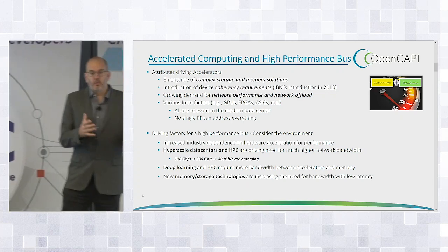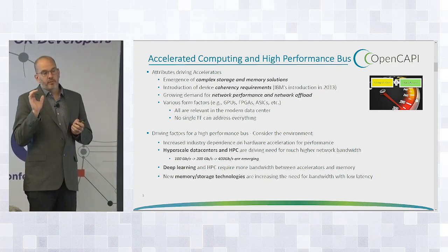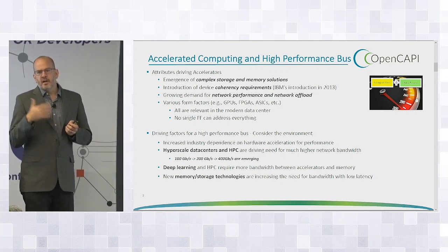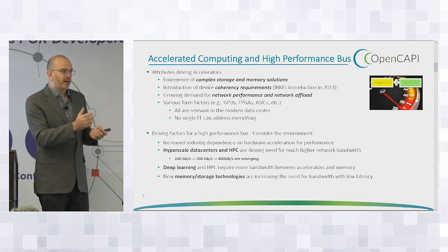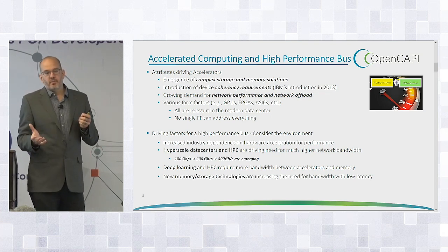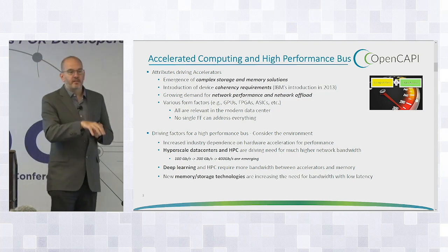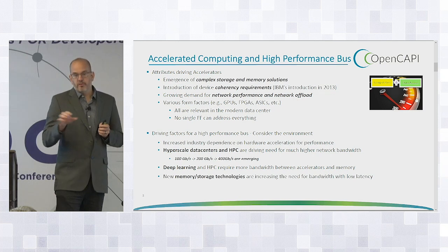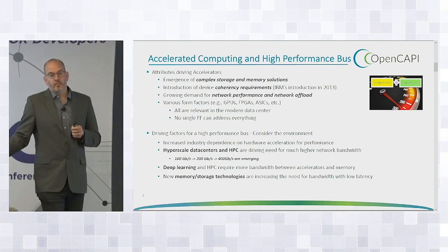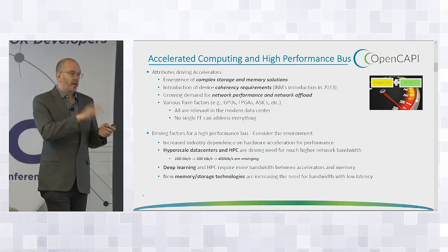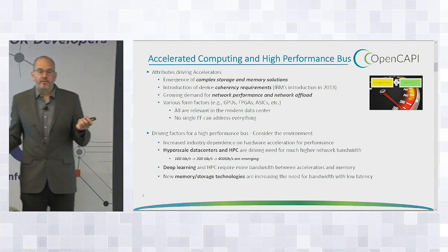So what does an accelerator want to be? And what we don't want it to be is a device that you talk to through a device driver that has high software overheads, that transfers a block of data to the accelerator, churns on it for a while, and then sends the data back. That very much limits the ways in which you can deploy accelerators. We need the accelerators to be tightly coupled to the host processor, and other accelerators in the system, and able to communicate through shared memory, right? So we want to be able to talk accelerator to accelerator, accelerator to host, through our shared memory model, just like multi-processor systems talk to each other.